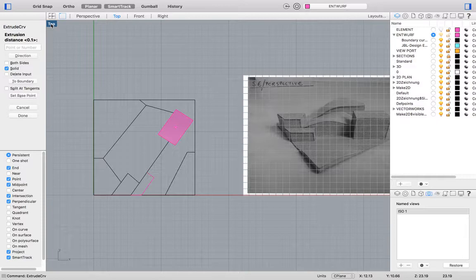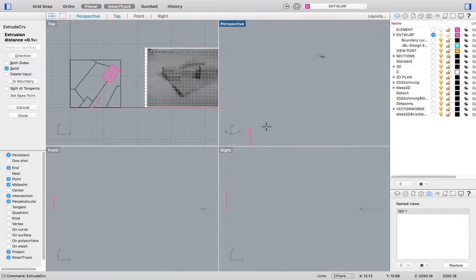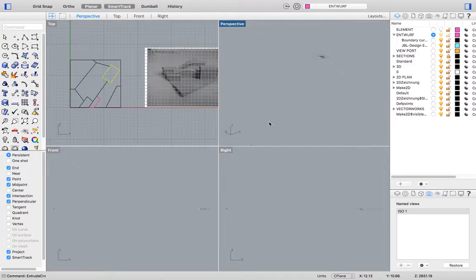Now, when you're modeling, always have your 4 selected views available to you, so you can see exactly what's happening in each view. Right now, I can see the larger model here. Simple command to turn that off, just temporarily, is hide, and that's hidden all the geometries that we don't need right now. We can get that back later by saying show.